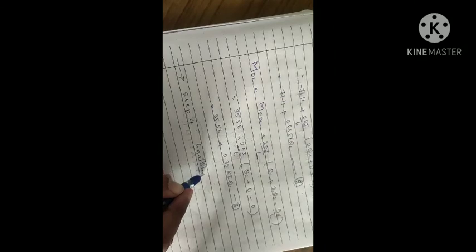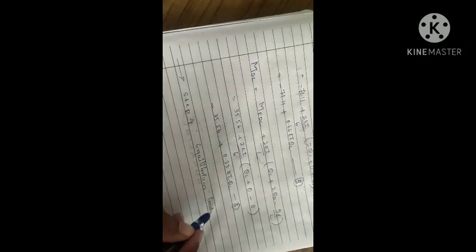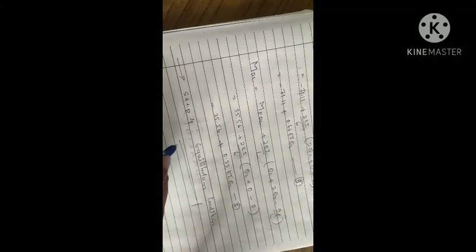4 is the equilibrium condition. Now I told you, the summation of moment at any intermediate joints or the rigid joints is equal to 0. For example, joints B and C are rigid joints or intermediate joints. So the summation of moment at B should be equal to 0. This means the moment developed at the MBA end plus MBC must be equal to 0. This is the equilibrium condition.